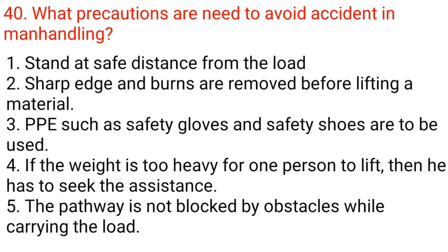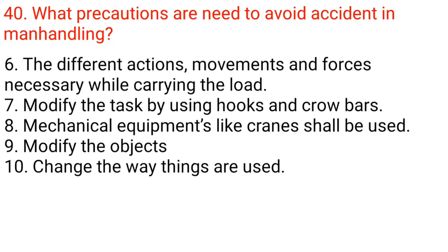1. Stand at a safe distance from the load. 2. Sharp edges and burrs are removed before lifting a material. 3. PPE such as safety gloves and safety shoes are to be used. 4. If the weight is too heavy for one person to lift, then he has to seek assistance. 5. The pathway is not blocked by obstacles while carrying the load. 6. Consider the different actions, movements and forces necessary while carrying the load.